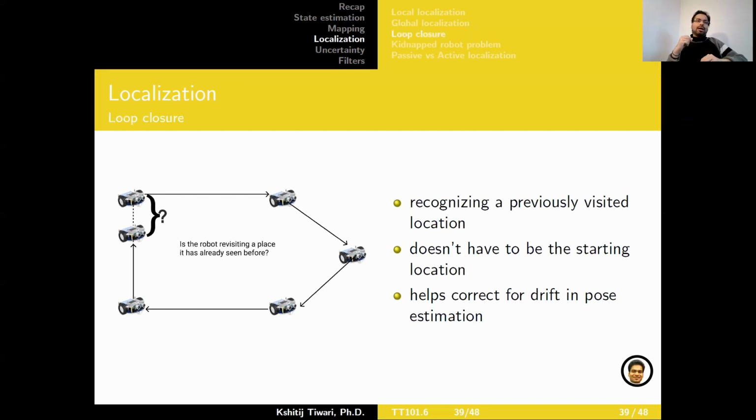Maybe your sensor goes down for a while, or maybe your camera or something is damaged, which basically means you get lost. You have no idea where you are, right? So suddenly it's a global localization problem. So what you could think about doing is trying to retrace your path and go to the last known location, and then start again from there, so that you have a sense of your bearing, where you are, what you're trying to do, so everything starts to fall back into place. So it's like a fail-safe.